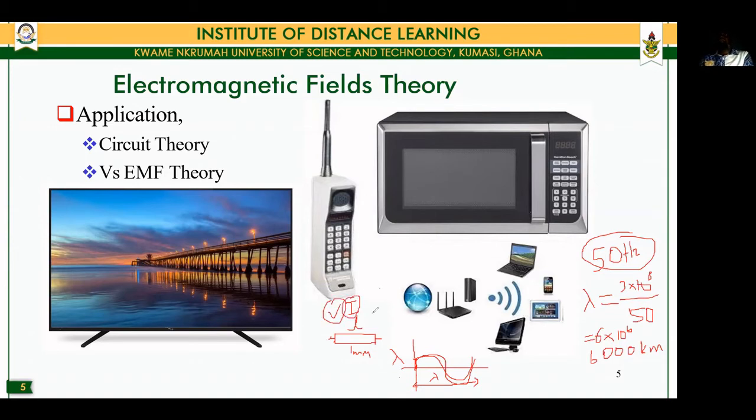So you can talk about 5 volts. You can talk about 2 ampere. They have specific values because they're constant. But if you consider a very short wavelength, let's say this wavelength is 1 micrometer, for example, then you can see that along this resistor, which is 1 millimeter, the wave would have changed several times from one end to the other.